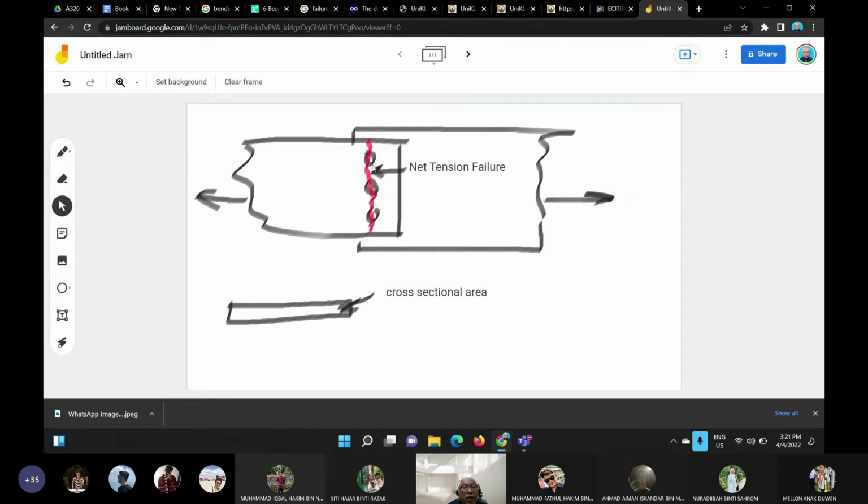If we cut the rivets, we drill a hole. When we drill a hole for the rivets, we have one here, we have one here, and you have another one here. So your area left is only between the rivets. Where you drill the hole there is no more area. Okay. So what is the shaded area? We call it net area.